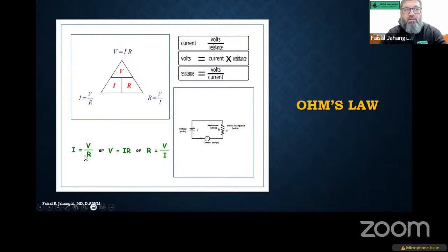If impedance is low, the voltage will decrease, and if your impedance is higher, the voltage will increase. That will keep the current constant. Constant current doesn't mean that you cannot change the current, but whatever current you set, if you stimulate at 20 milliamperes or 50 milliamperes, that current flow will not change in the circuit, but the voltage will change depending on the resistance of the electrode.